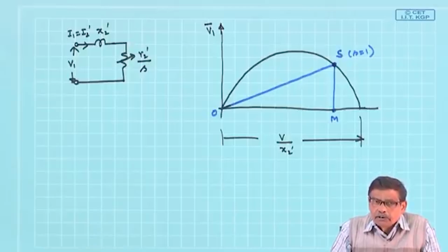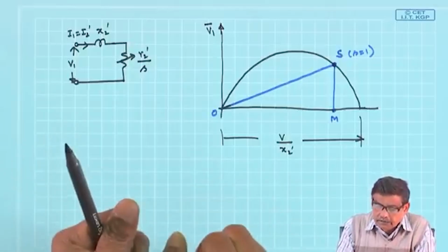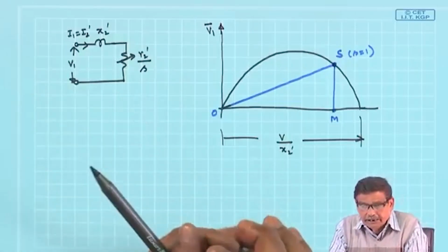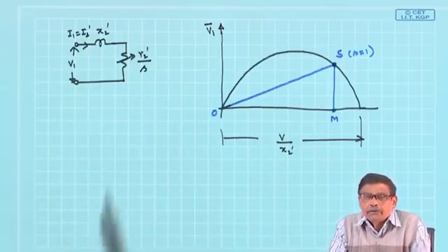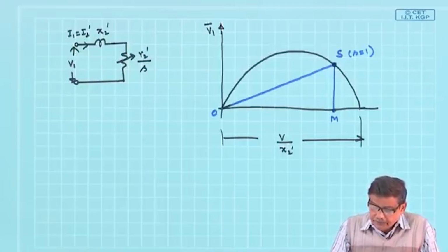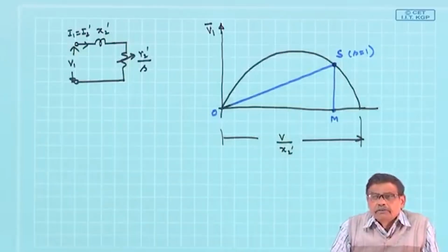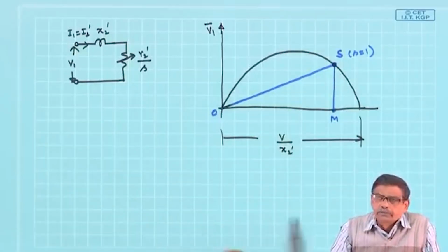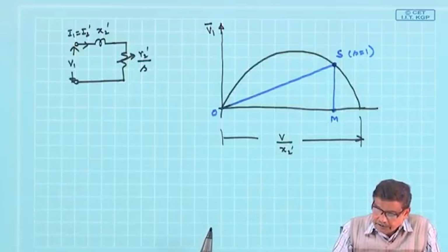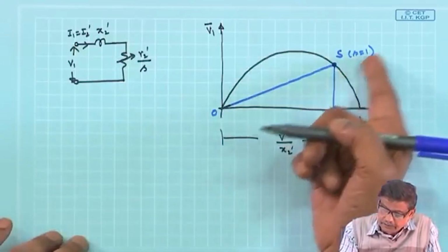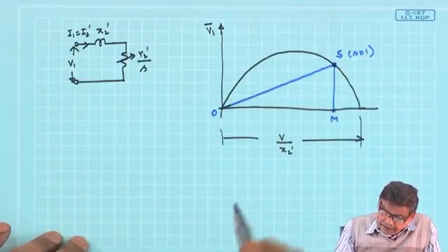If someone wants to hold the rotor with applied voltage, he will feel the punch of that; it is trying to rotate, you are obstructing that. It has developed torque, but you are not allowing it to run. Therefore, no question of any mechanical output power comes in, and N R equal to 0, that is why slip is equal to 1.